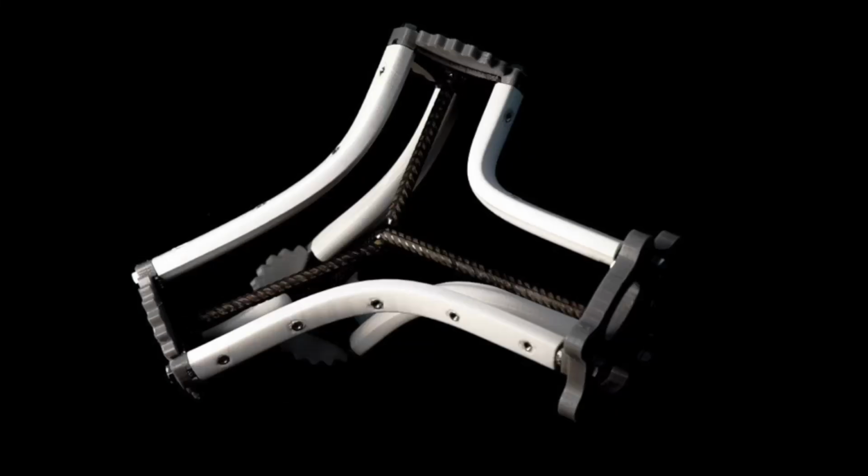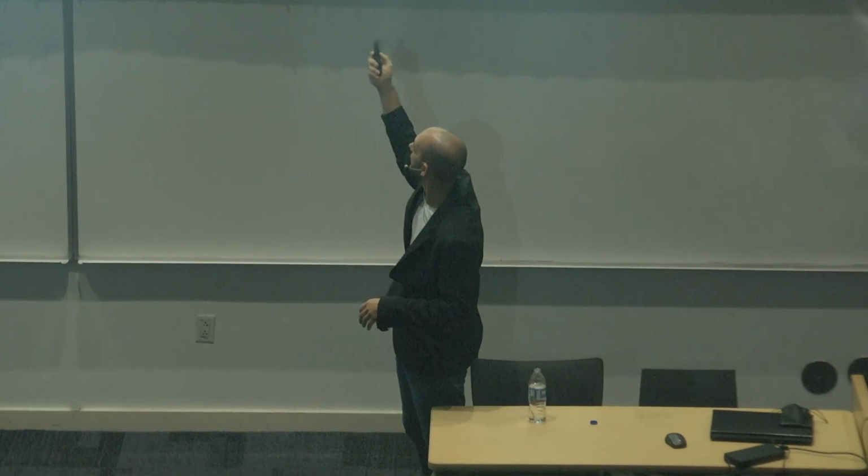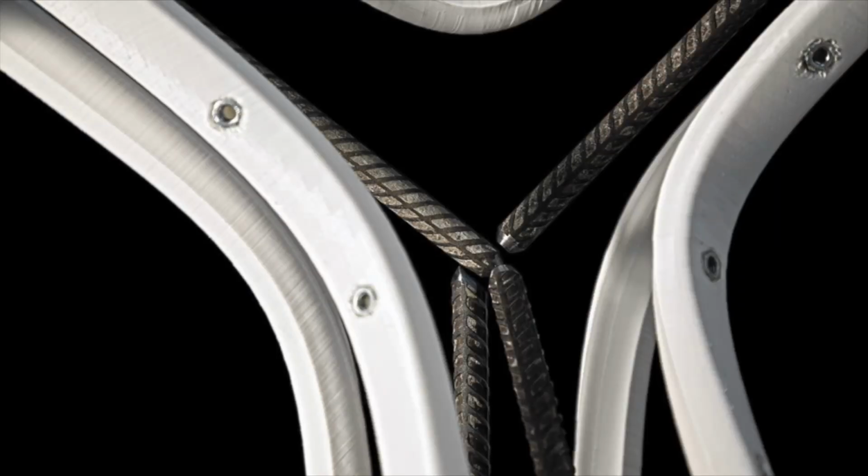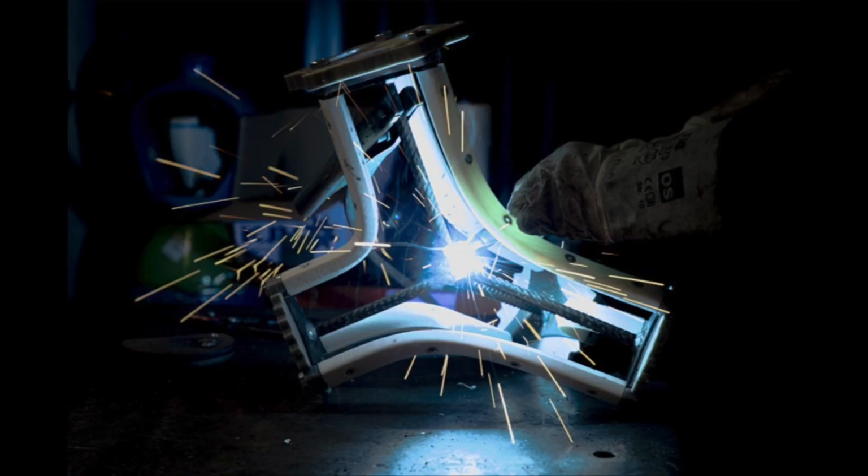We see here that we were producing those 3D printed elements that were keeping in position a system of reinforcement bars. So on every face, on every end, we have a steel plate that has a bar welded at the base of the plate, and then they are positioned in order to allow a person to weld at the center. So you see here a detail of the different bars that are converging to the center, and this system of arches of 3D printed elements creates enough openings for an operator to go there and actually weld the bars. So here you see the operator welding them.